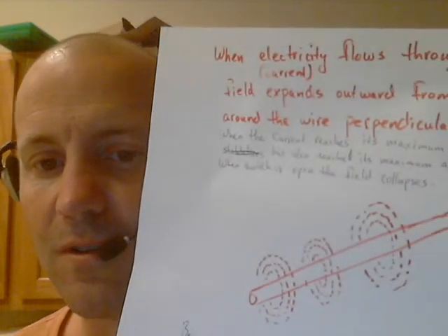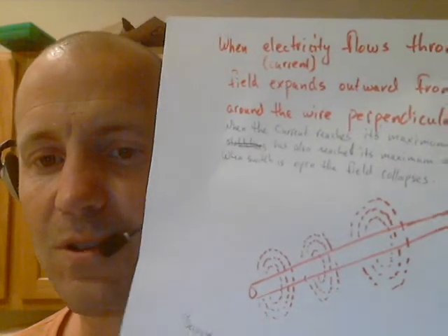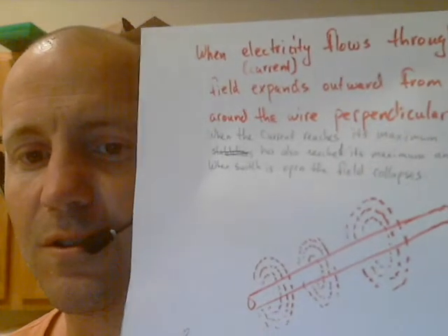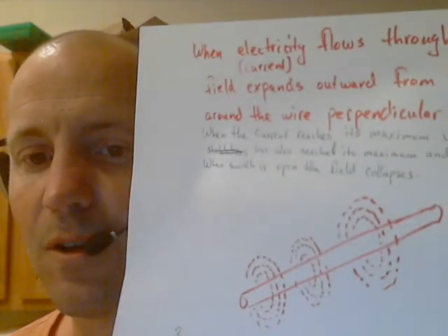Now, in a DC circuit, this phenomenon isn't particularly useful in most cases, but in an AC circuit, what happens to the current? Just a quick review here: in an AC circuit, as the voltage is continually changing, going to its maximum in one direction, then back to zero, and then to a maximum in the other direction, the current is also doing the same thing.